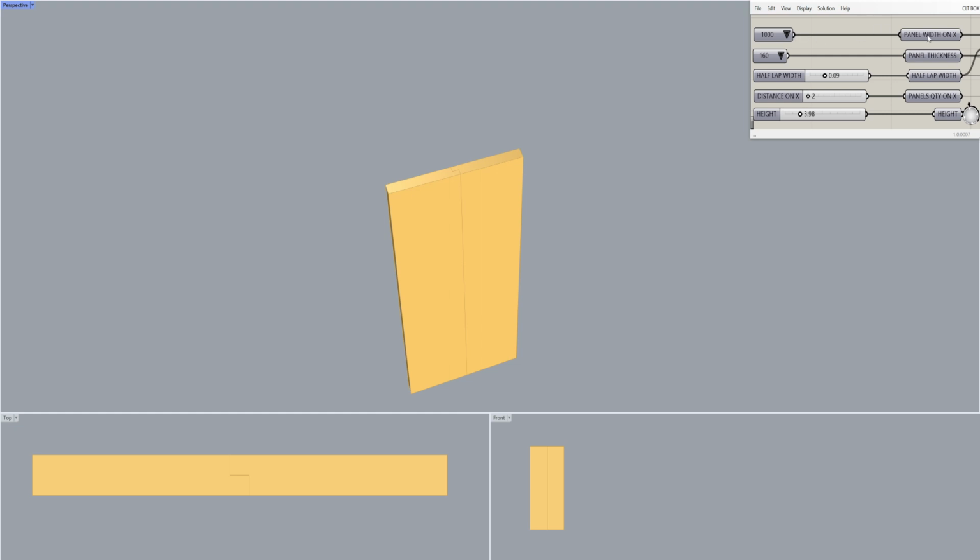So in this case, for example, here I have a panel width. In this case it is on the x-axis, as this is going to be part of a larger CLT box design. We'll have it on the y, and we'll also have a slab. What I refer to here as panel width is 1000, 2500, 2730, 2950, and these can just be whatever standard sizes the manufacturer is using, and it will depend on who you use. These are based off of KLH standard sizes, not the 1000. That's just easier to visualize.